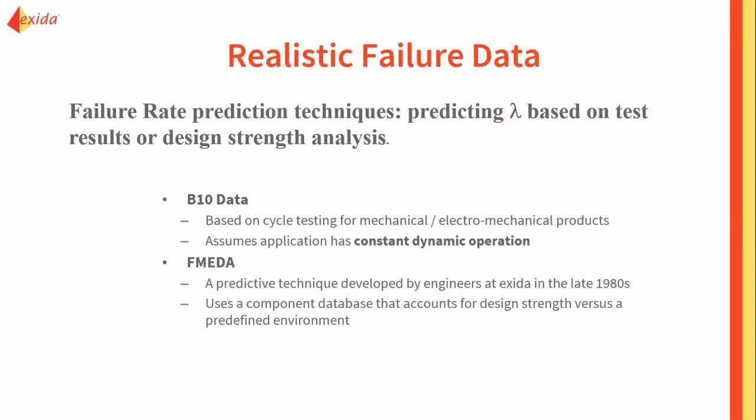The other way of predicting failure rates is the FMEDA technique. That stands for Failure Mode Effect and Diagnostic Analysis. And this is looking at design strength versus all of the stresses for a predefined environment with a predefined device.